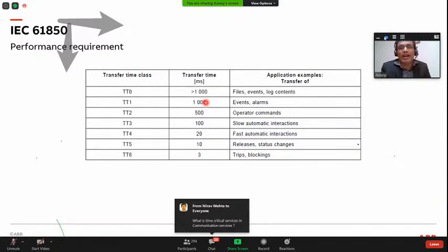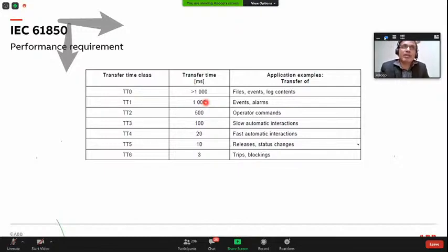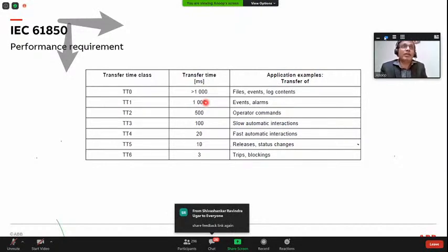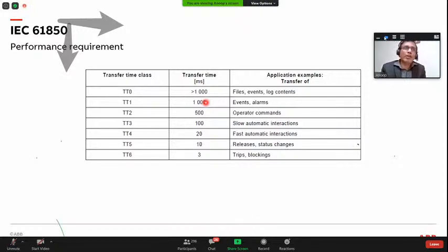So I'll just summarize what I've explained until now. We touched upon substation automation functions: protection, control, and monitoring. If you remember, there are overcurrent protection and fault protection. Control means you're closing and opening the switches, which are called circuit breakers. Monitoring means you're monitoring your current, voltage, and temperature.